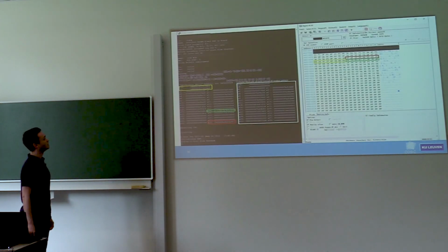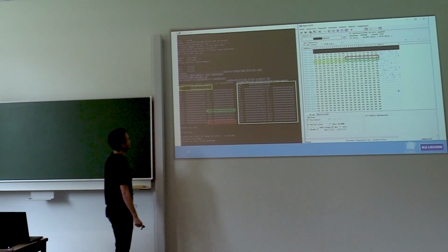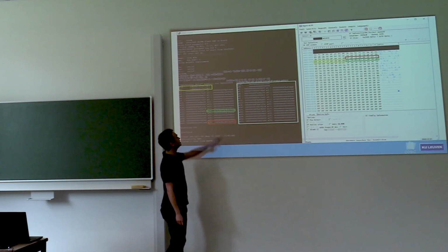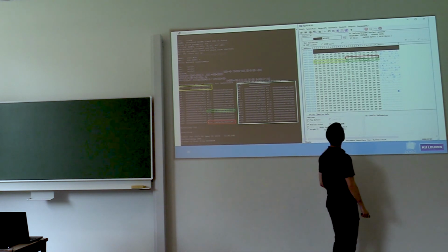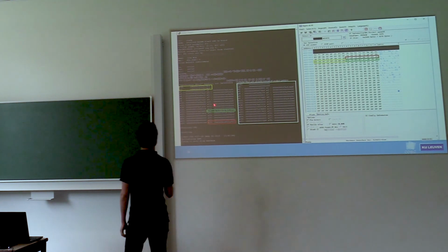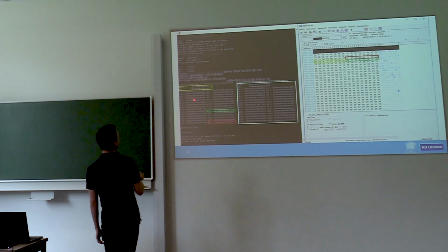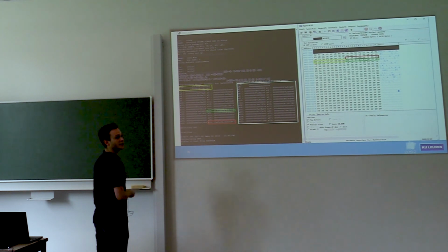So this is what this looks like. When the device crashes, it prints all of the contents of all of the registers. And this screen shows whatever I wrote to the EEPROM. So you can see that the link register contains EDBD, and that's the same thing that I circled here, but it's in the reverse order because of the endianness.